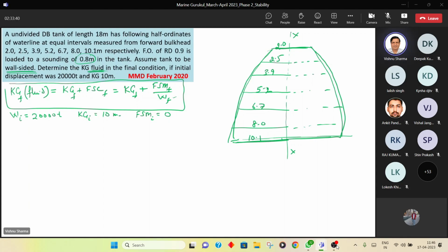We'll make the table. Okay? Now why with half ordinates? Because you also have to get the moment of inertia of this area about XX, and that can happen only when you take half ordinates. Am I clear, beta? Guys, clear why we have taken this decision? Okay, what is it that you did not get? Tell me. Half ordinates are given in the question. What is it that you have not got? Tell me that. So here the area we will calculate with half ordinates only.